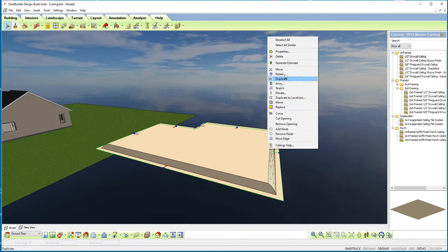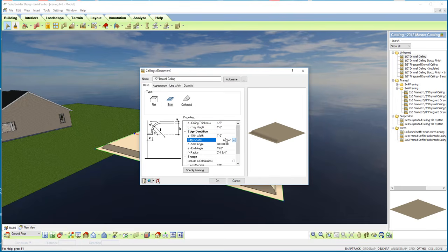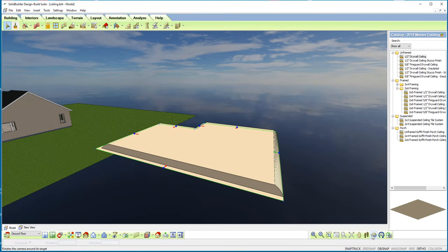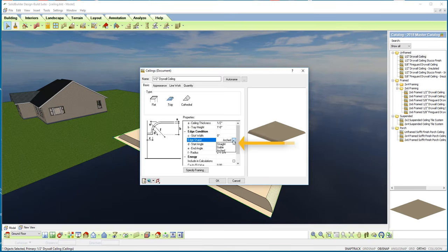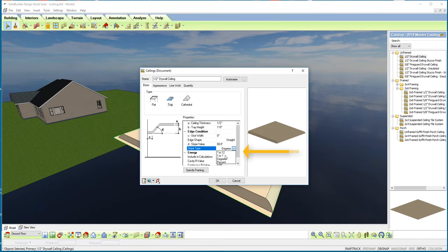I can also reduce the skirt width to 0, and then the arch will be occurring directly at the wall itself. This can be done simultaneously as you're selecting multiple arrows. The other option that we have, if I go back to the straight, is to switch from degrees, and then we have these various options, percent in one end, and then a pitch per 12.